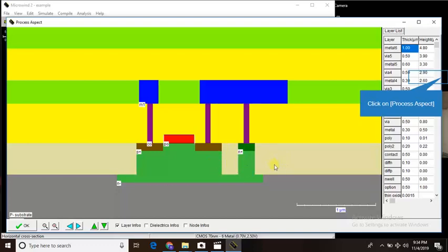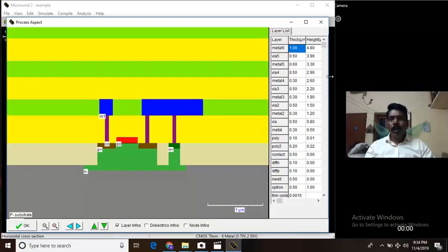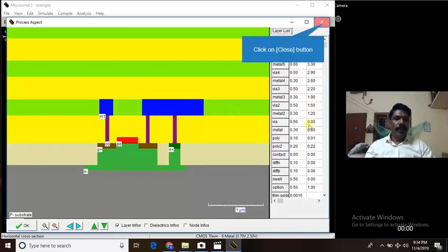Okay, so what is this? This is a thick oxide. This is the active area, where the thick oxide is not there, and the field area is where you have a thick oxide. In the active area, no thick oxide is there, only gate oxide, very thin oxide. So this is how you can also verify. For learning purposes, you can see how the cross-sectional diagrams of the devices look, and the dimensions and heights of various layers are given here.